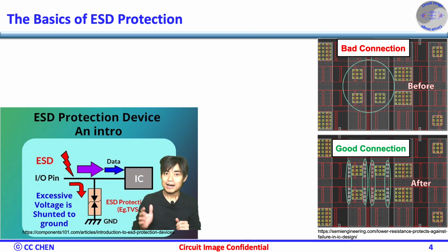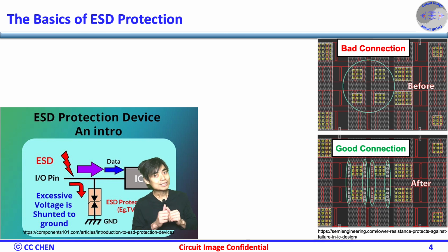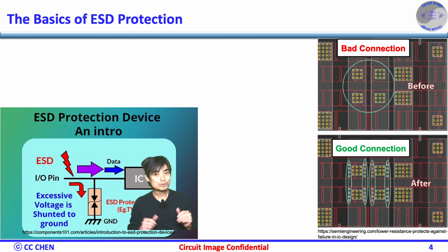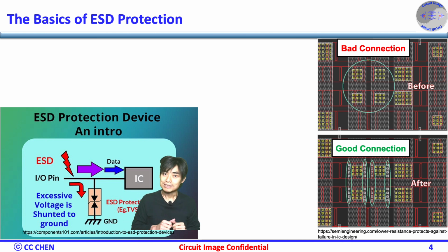Power clamps act as high-speed switches that limit voltage spikes. Resistance in series can slow down discharge paths, protecting delicate nodes. Grounding techniques can play a role in reducing ESD risks. Even PCB material choice affects how well a circuit can dissipate ESD. Shielding and enclosure design contribute to overall system-level protection. Proper routing ensures that protection elements act before the IC is exposed.